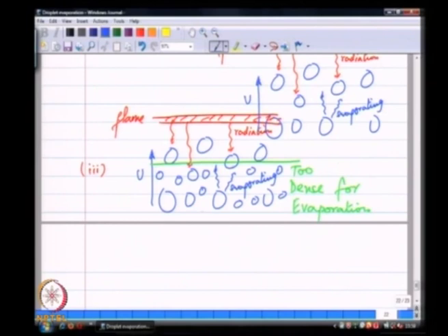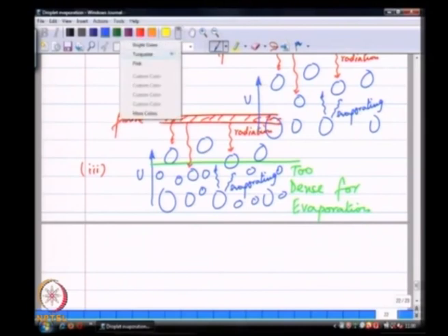When you are in this too dense for evaporation regime, you tend to have non vaporizing droplets that, during the course of a typical spray which has a diverging angle, an angle of divergence to the cone encompassing all the droplets, experience an increasing cross sectional area available for the droplet flow. As a result the droplet spacing is increasing, and in that increasing droplet spacing sense you tend to create vaporizing droplets.